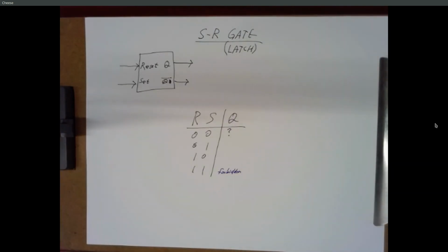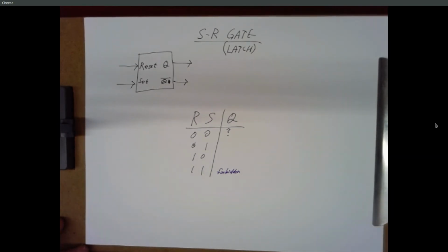Is this kind of how a reset switch works? It's exactly what a reset switch does, yeah. You either have a big red button that says reset, or you wire something into the power supply so that when the power comes from 0 to slowly hit 5 volts, it forces a signal into, say, the reset line. So yeah, that's exactly what a reset does.